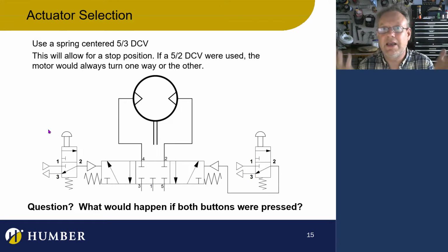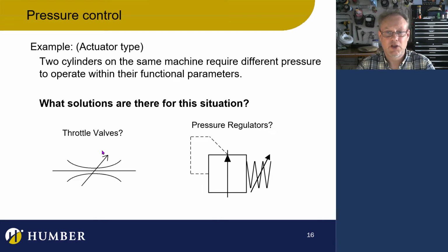I really don't know. I'm just making this application up. I've never actually seen one of these. I'm just imagining an application. And how would you get a pneumatic motor to stir paint on a cart when an operator needs to do this? Well, you would do it this way. And it's up to you to choose which center you want for your 5/3 valve. There you go.